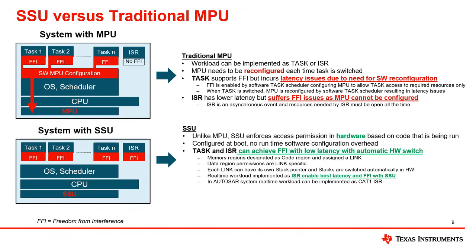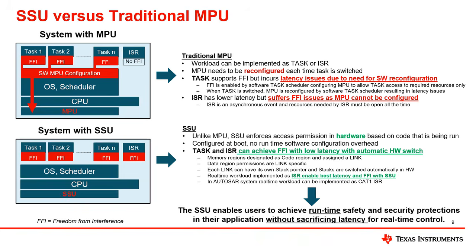For SSU, this switch of protections is happening in hardware, so there's no extra cycles or added latency that occurs. This is how the SSU is able to achieve runtime safety and security protections in an application without sacrificing the latency for real-time control.